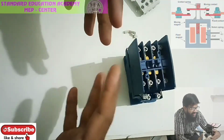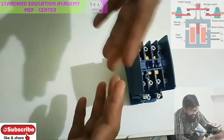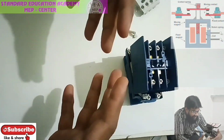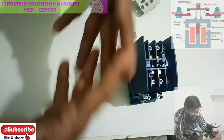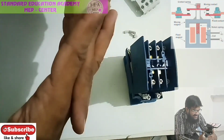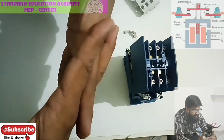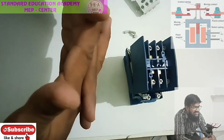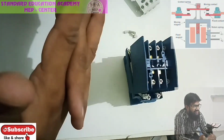Consider this hand as source, this hand as load. Whenever the coil is getting energized, there will be a contact created between these two hands and they will get interlocked. As they got interlocked, definitely supply from L1, L2, L3 will be given to T1, T2, T3. That's how a contactor works with energizing a coil.